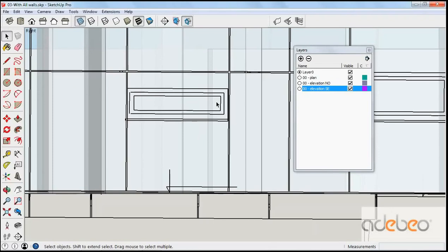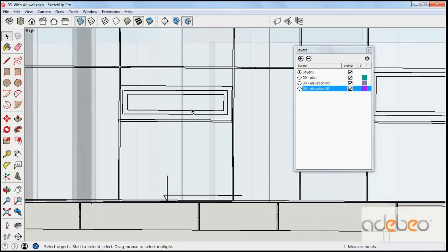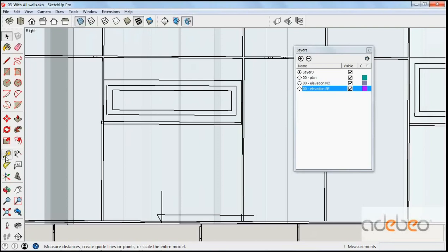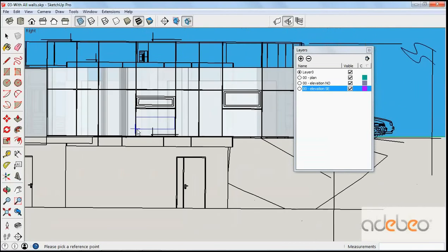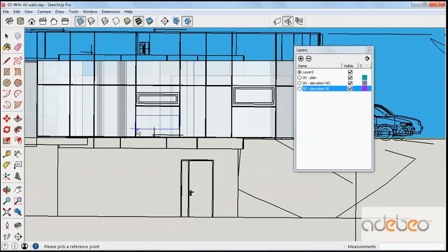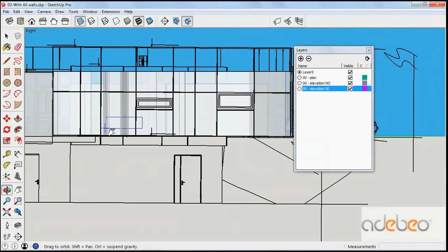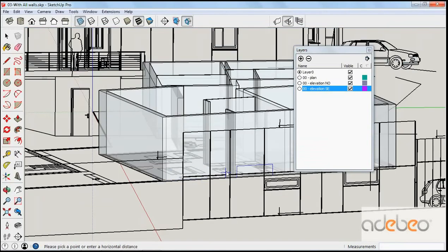Define, 180. So go to the create opening button, width 180 centimeter and 55. So create opening. You see that the opening has already been created, but it needs the vertical and horizontal position. In order to do that, we need to first select the wall where we are going to place it, and then we need to locate it.